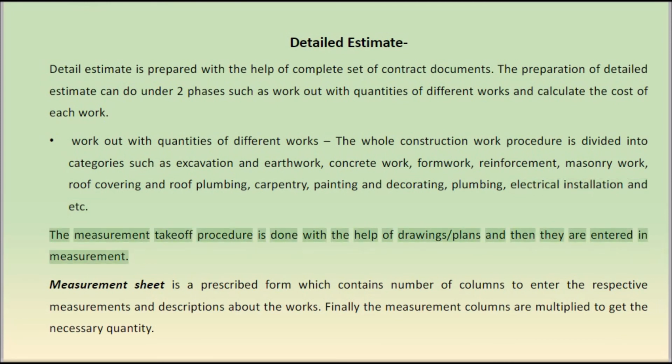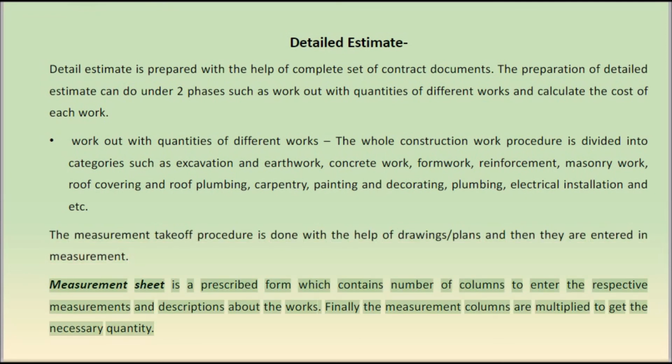The measurement takeoff procedure is done with the help of drawings and plans, and the values are then entered in the measurement sheet. The measurement sheet is a prescribed form which contains a number of columns to enter the respective measurements and descriptions about the works. Finally, the measurement columns are multiplied to get the necessary quantity.